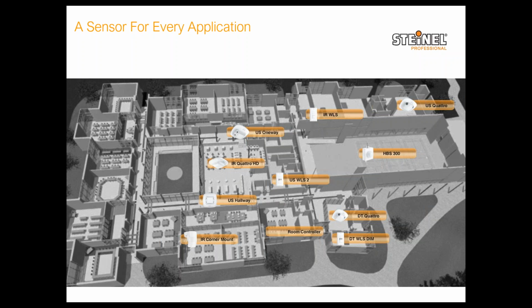Then a little bit to the left, we have the IR wall switch for small janitor's closets and small storage rooms. You just want to make sure that as long as you're moving stuff around or taking something out of that small room, you're in line of detection. There are no complicated situations there. High bay sensors for the gymnasium area where you have the high ceiling. You definitely can't be using ultrasonic. Movements are quite big, so even a simple PIR sensor will get the job done.